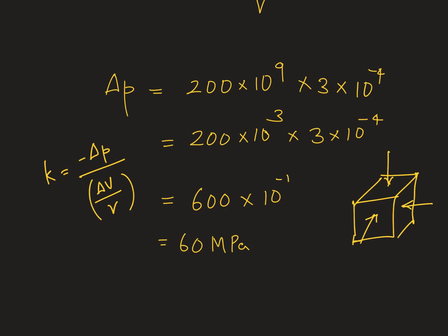Now the rest of the things is fairly easy. You know this value, you know the bulk modulus, but one thing, as I usually say, have a consistent set of units. Here I plugged it in MPa. Again, a small correction: in the question it was given as 200 GPa, and I changed it into MPa so that I get the stress in Newton per mm square, or in MPa again. So this is a consistent set of units that I usually use.